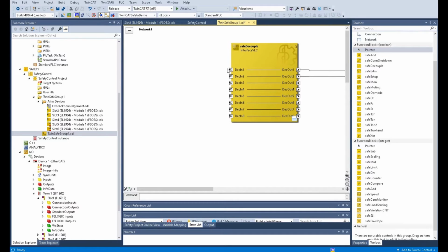So firstly, we will name it. For example, that is the vertical light curtain channel A. And this is channel B. We name these channels first. I will introduce how we can connect these names to the physical terminals.